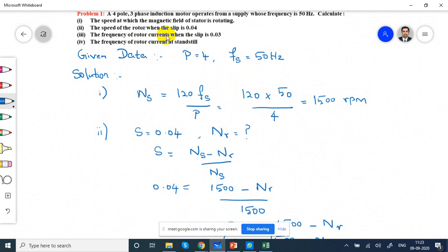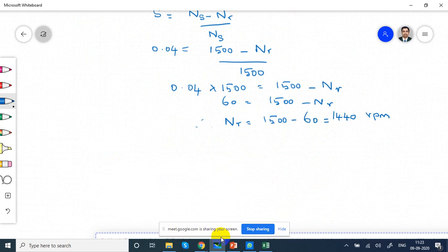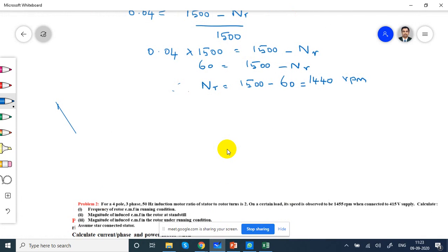What is the third one? The frequency of rotor current when the slip is 0.03. That is my third one. Third subdivision, frequency of rotor current. That is Fr equal to how much? S equal to 0.03. So we know that the frequency of rotor current Fr equal to...